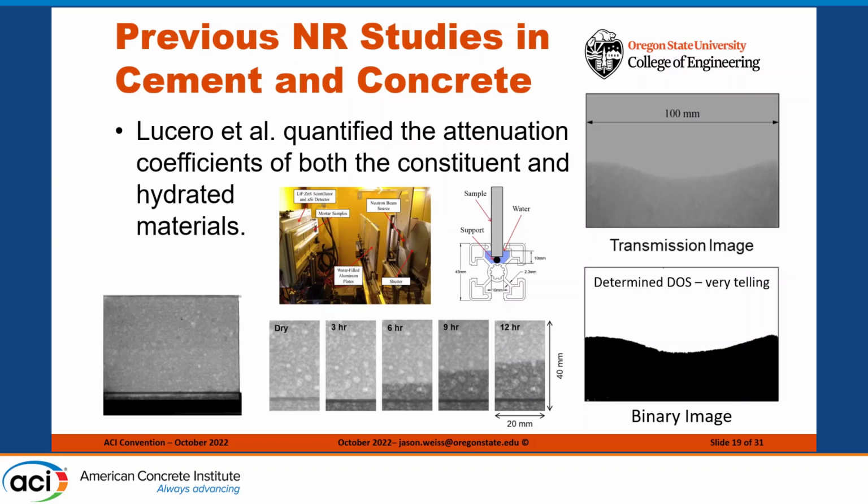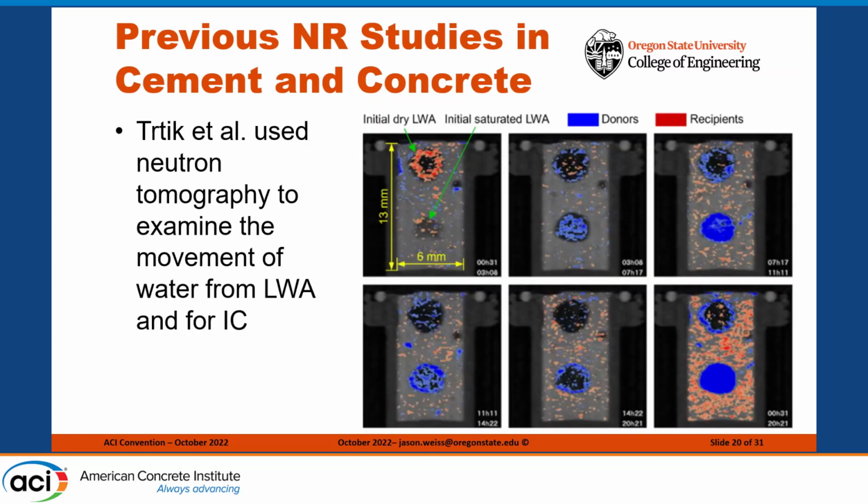And one of the things that's very interesting is the absorption of water has a two-phased approach. We fill in the really tiny and the medium-sized pores very quickly, and it takes a much longer time to go back and fill in the larger pores under capillary sorption. So she was able to start to develop models that could describe how fast the water was entering the system and really quantifying this in terms of degree of saturation, which is really important for things like freeze thaw.